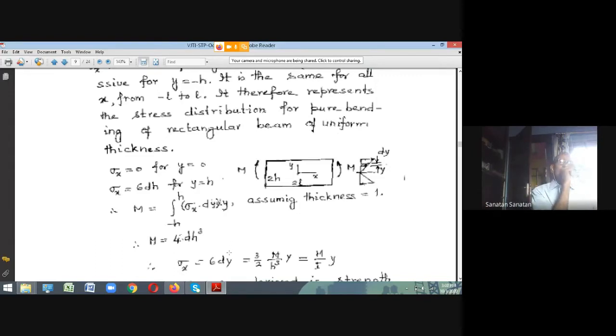See, the point is like this. Phi should have a form which, irrespective of the form of that function in terms of x and y, will satisfy the equilibrium equations. But when you satisfy those equilibrium equations and put in the values, you will find that the constants involved have some interlinkage. They have some constraints on them. They cannot be just arbitrary. They must be such that they make those equations equal to 0. That is one aspect. The second aspect is that the equilibrium equations must be satisfied.